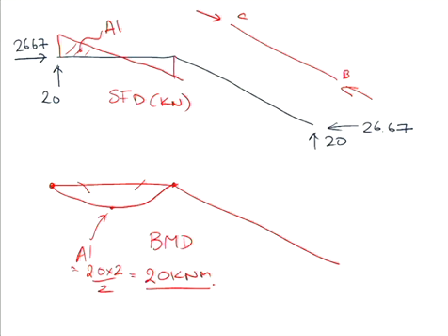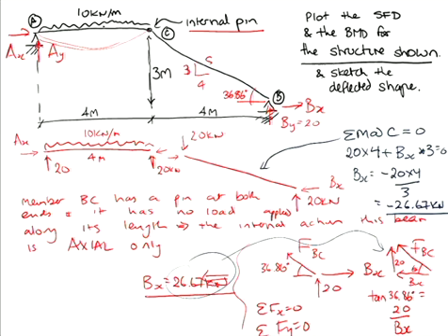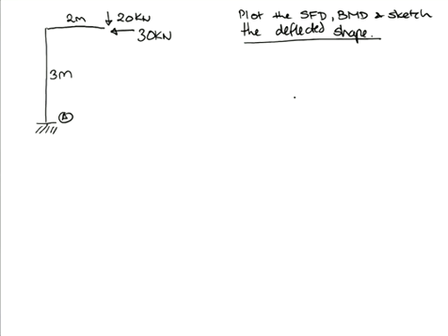Did people who did it at home get that? Yeah? Well done. So it's a simple one. It's a question that initially you go, oh my God, what am I going to do? It's forces at angles. And the shear force bending moment diagram is very simple. So the load is being transferred through member AC here in bending and shear. The structural action in member AC is bending and shear. The structural action in BC is axial loading. So that was a fairly easy one. With this one here, to those 5 that did it, I apologise.